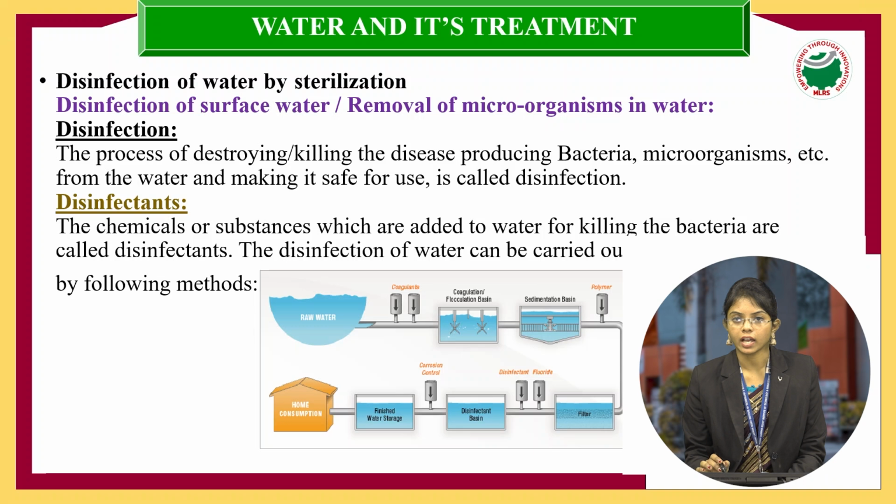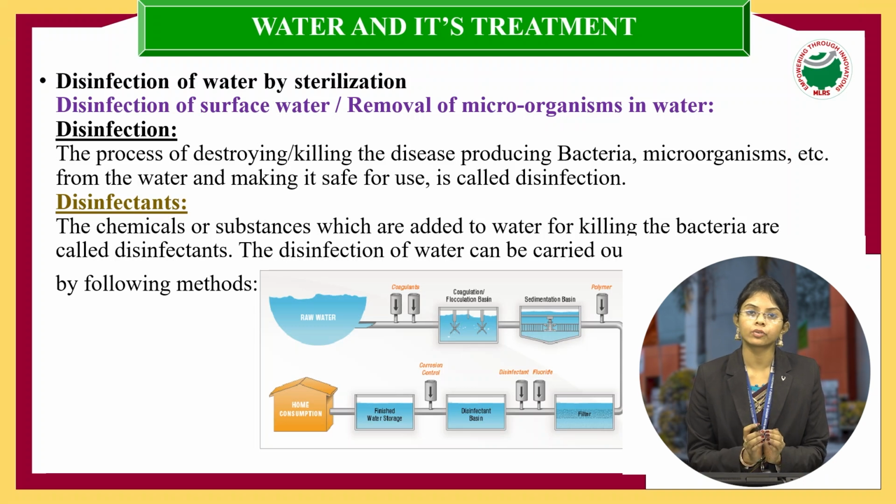Till filtration we have seen that we take water from the source, and next the water is sent to screening, and from screening to aeration, to coagulation and flocculation. Now in flocculation, larger flocks are formed. Now these larger flocks with the water we send to sedimentation. These larger flocks are settled down. Whatever flocks are settled down are removed easily and the water is moved to the filtration.